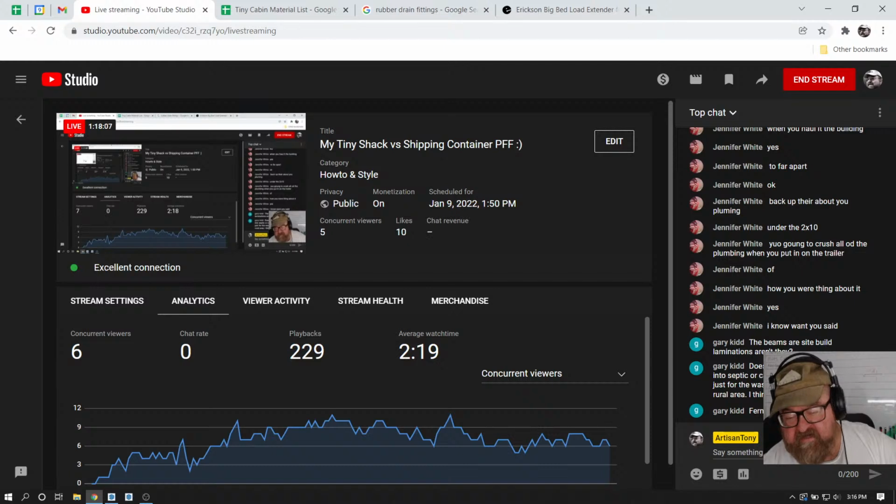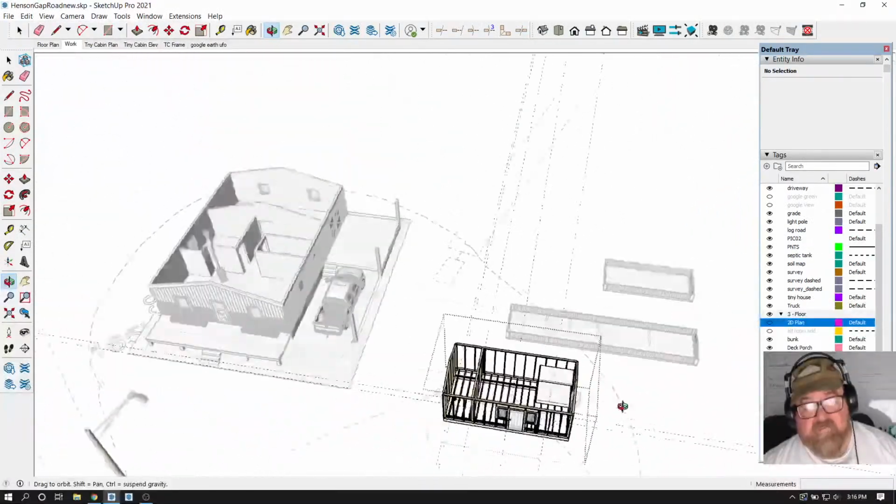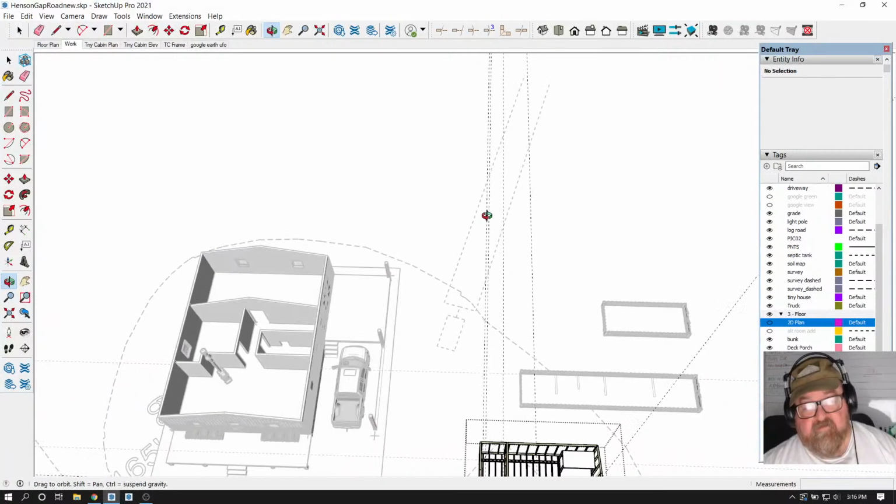Fernco fittings, yes, that's a brand. Does your washer water need to go in the septic? It used to be permitted in a rural area. I think a 50-foot field line was okay. I'm going to have two 80-foot runs. I need to check with my septic tank guy, but that's what I've got drawn now.